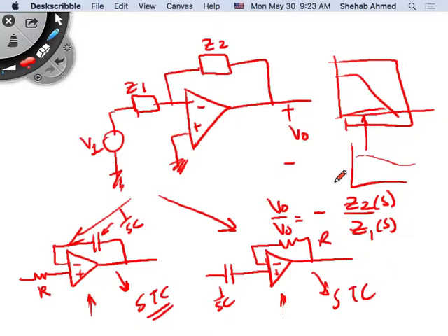So I cannot just look at this frequency domain plot of magnitude and phase and tell you what is the output. You have to derive the time domain representation of the output. And that's what we spent time on yesterday. So we looked at the current flowing, we looked at the V output being the voltage across the capacitor. In this case, we had current flowing through here. So we found the relationship between current and voltage across a capacitor.